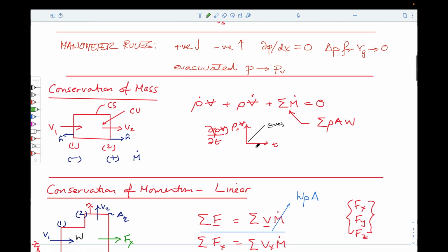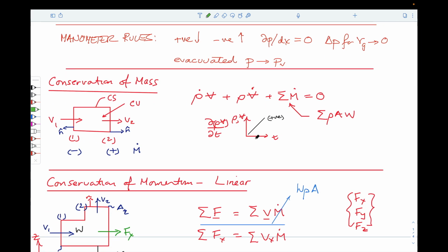Dealt with in the earlier part of our course, we talked about manometer rules in going up and down through fluids. If we go down through a fluid, we add fluid pressures. If we go up through a fluid, we subtract fluid pressures. If we go across a fluid between 2 locations that are the same elevation but are simply connected, then the pressure doesn't change.